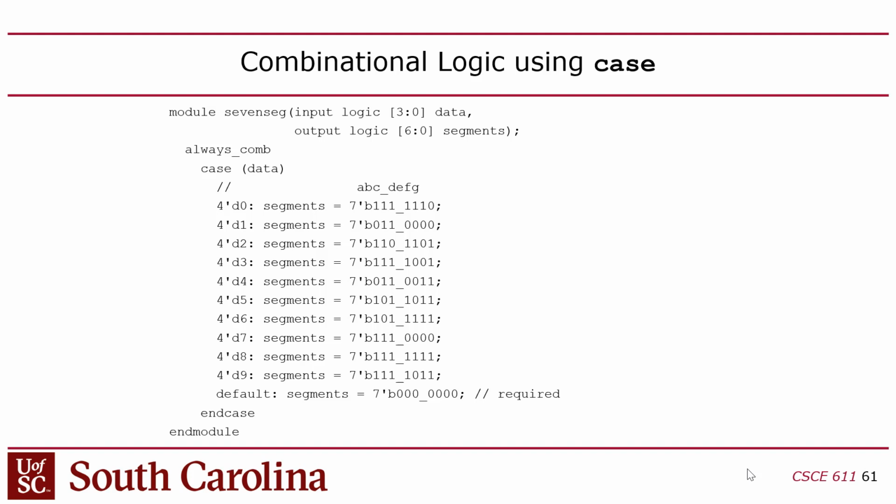So you have to kind of reverse the order. And finally, the 7-segment displays on this board are active low, which means you set the segments to 0 to turn them on and 1 to turn them off. And this assumes active high. So you can make those changes, and you can use this as a starting point, but you're going to have to make a few changes on these boards.